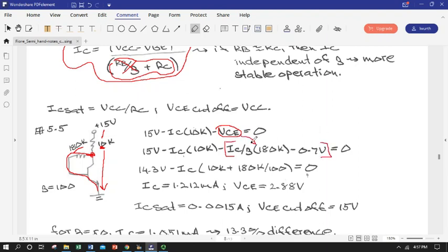So all of that is the CE, because that's another way of getting from the collector to the emitter, and in this case, of course, the emitter is at ground. So VCE is the same as V sub C. So that's basically the drop through this path, which we know. We know all of the values. Base emitter junction, we can write an expression for the base current in terms of the collector current using our beta, and we know our base resistor value. So we end up getting this expression with just I sub C.